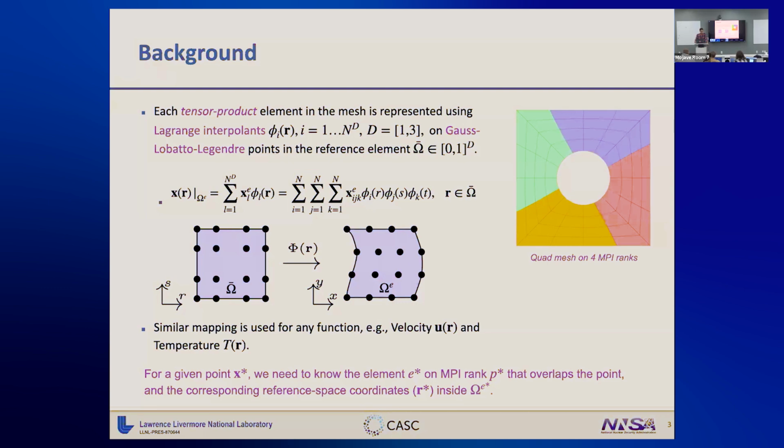And you see, if you use this combination, you get this summation. The first one shows the coefficients are the nodal locations in physical space. You have your basis functions for tensor product elements. You have n to the d nodes or basis functions where n is based on the polynomial order.